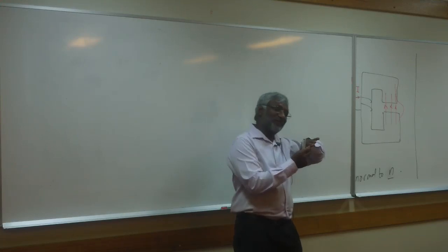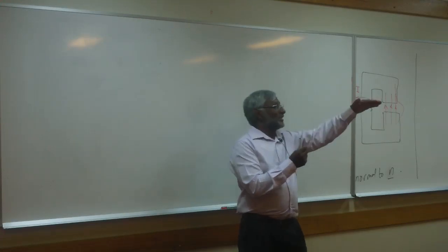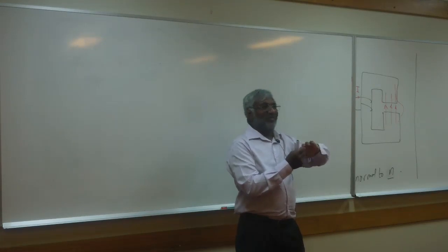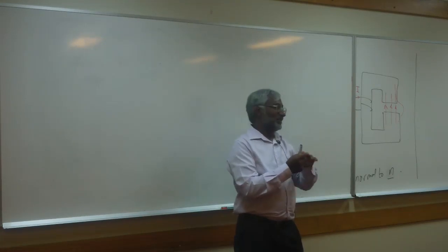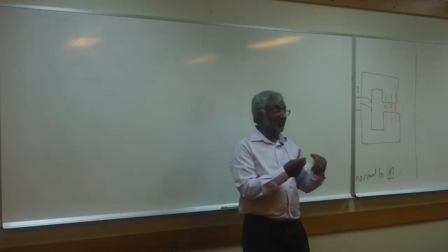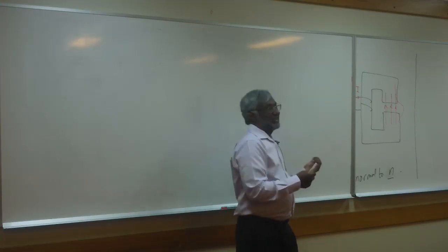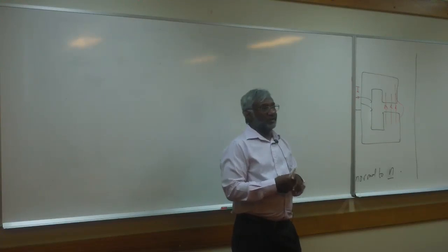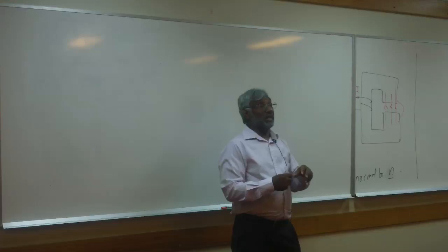There are situations where that straight line becomes nonlinear, becomes a curve. And we gave an example, and the example we gave was the surge diverter, or the MOV. Similarly here with inductance, it's a straight line, yes, for cases where you keep getting more and more flux as you push more and more current.